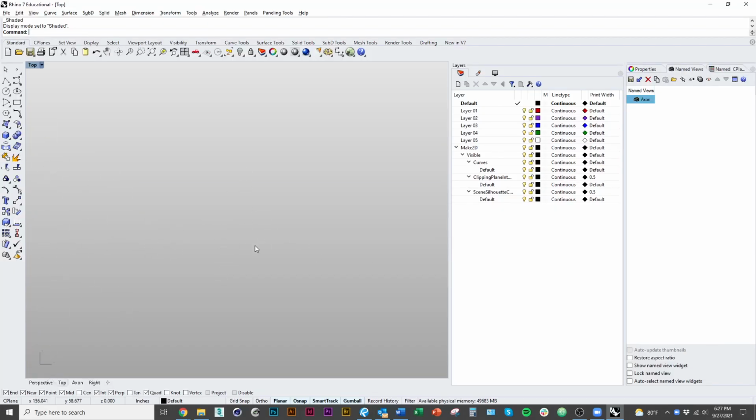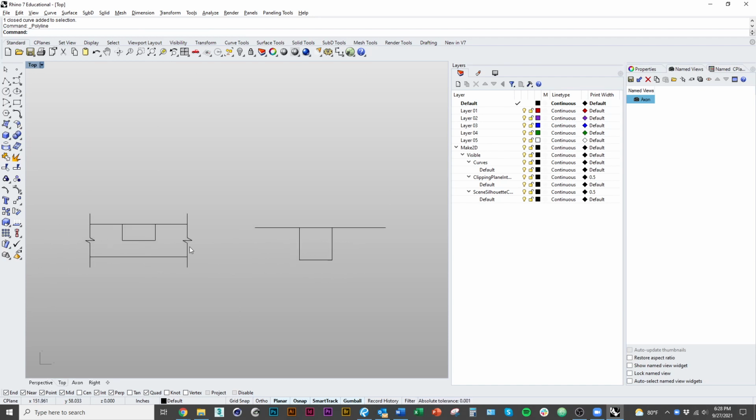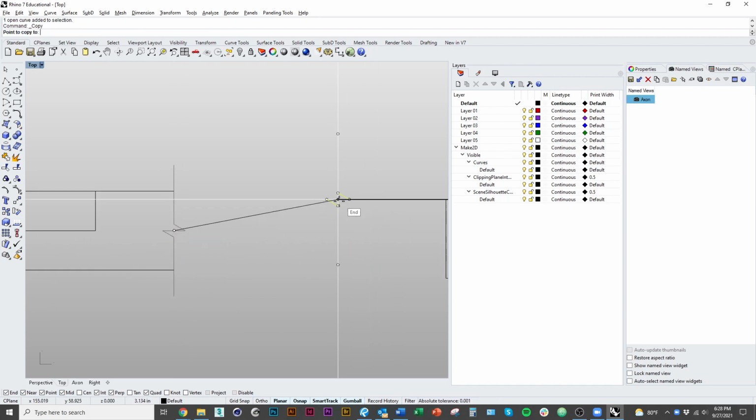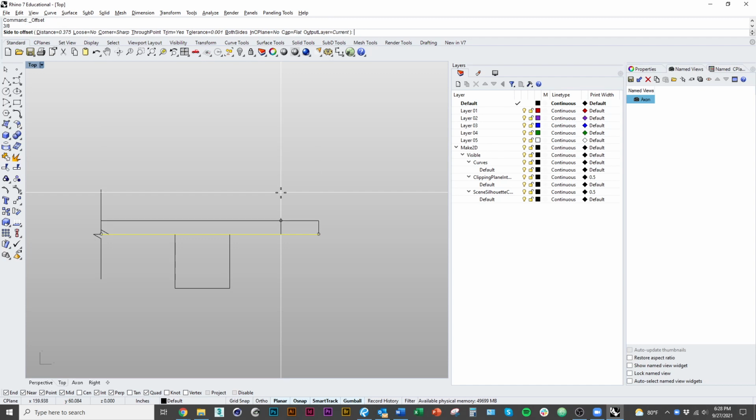Okay. So once again, we'll draw the cross-section of the member, 1.5" square, 1.5, enter. And I'm just hitting enter twice to use that same dimension both times. And then we would want to show the seat. Seat comes across somewhere. Again, we could use this. And seat is, I forget, it was 3/8. We'll make it 3/8.